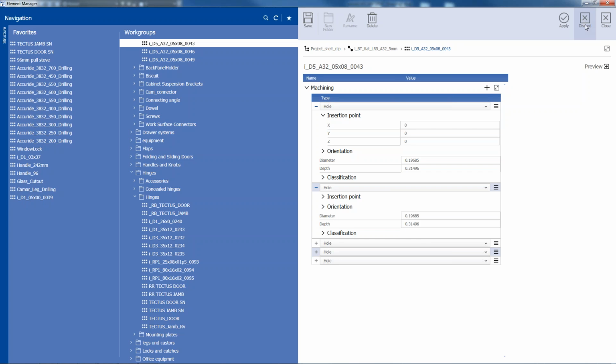It's which connector is actually being used. The one that's set up as the default doesn't have machining because you're doing full line boring. If you don't want to do full line boring, then you have to pick that other shelf and it automatically has the 5 holes set to it. But we can make it however many holes you want. All right, not that this is our standard, but quite often customers like to have just a couple of holes per shelf.